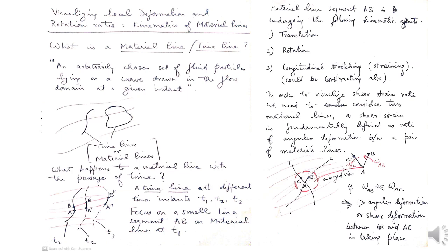And as per the figure, you can see that the distances are increasing. But it could very well have been contraction also going on. So this figure explains that the distances can change between two neighboring fluid particles on a timeline as it moves. And not only are these distances changing, which gives a hint of what you call local strain rate.